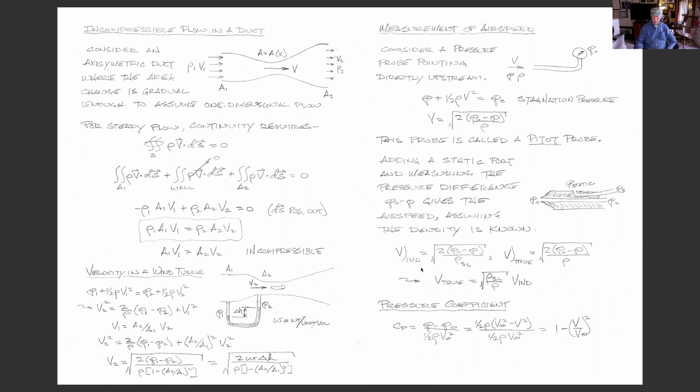Now, as you go up in altitude, on that standard day, the true airspeed's the same. But now you climb up to 10,000 feet, your true airspeed is higher. And at 20,000 feet, your true airspeed is still higher.